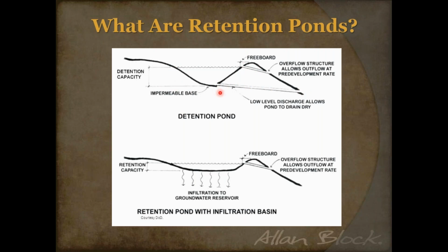You've got that impermeable base, so it can't seep down. So you are really confining or detaining that. Obviously, there are engineered controls for overflow and stuff in most of your pond applications. And that holds true for your retention. Retention, what you're trying to do is you're retaining that. So you're in fact holding it, and the goal is to actually recharge the groundwater reservoir, the aquifer below grade, so you're hoping that seeps through and into your groundwater source. Again, you still have your engineered overflow practices that need to come into play. So those are kind of detention and retention characteristics.